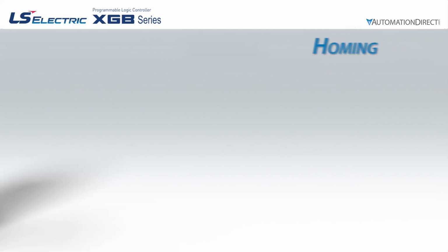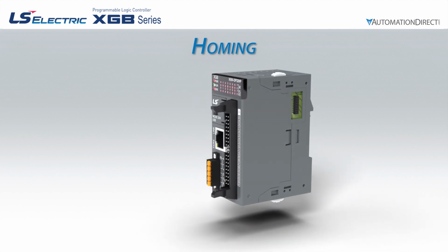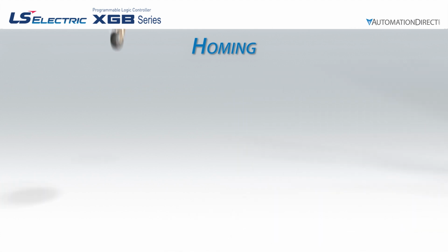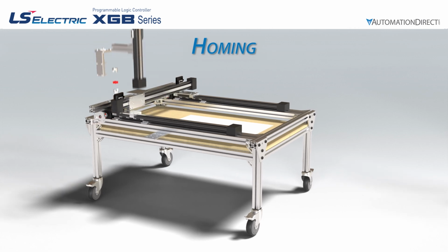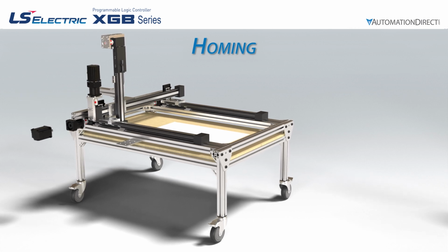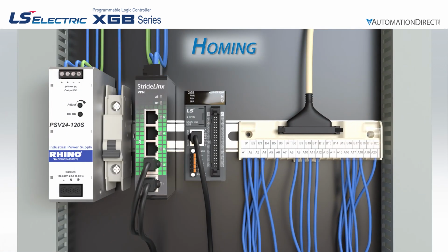Let's look at a motion application with the LS Electric XGB PLC. For this example, we will be using a 3-axis motion system which utilizes many components offered at AutomationDirect.com. Our system is built on a Sure-Frame extruded aluminum base with casters. It utilizes IGUS drylin actuators and Sure-Motion couplers from AutomationDirect attached to LS Electric gearboxes driven by L7P servo drives and motors. These drives are controlled by pulse train outputs from an XEM-DN32HP 6-axis motion controller.